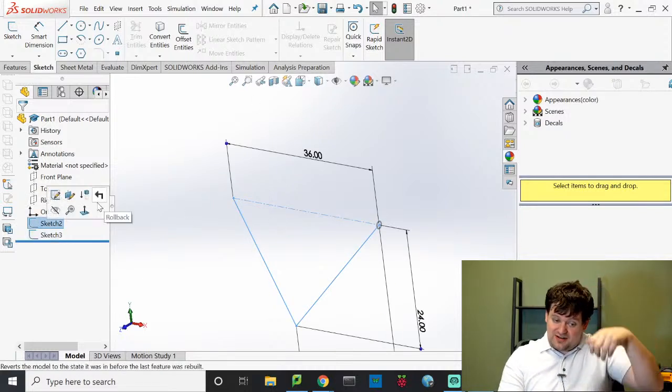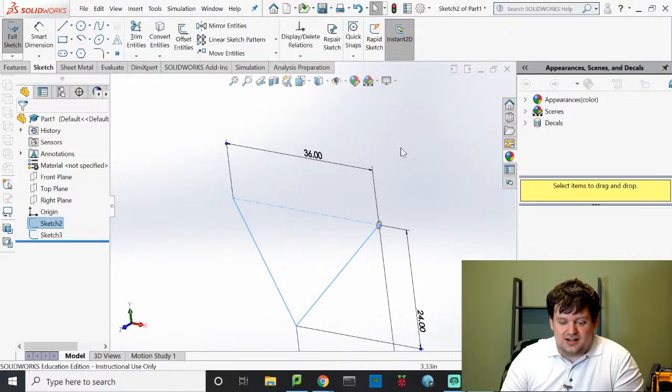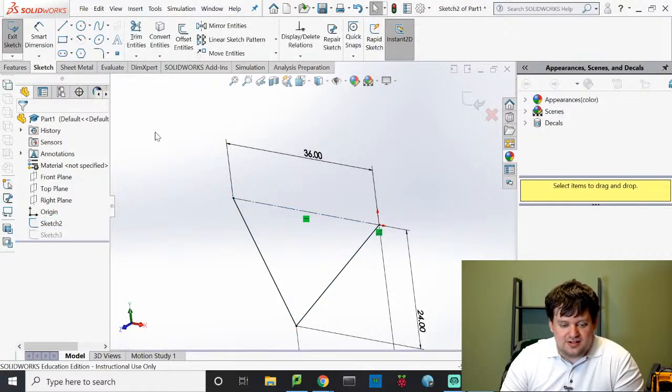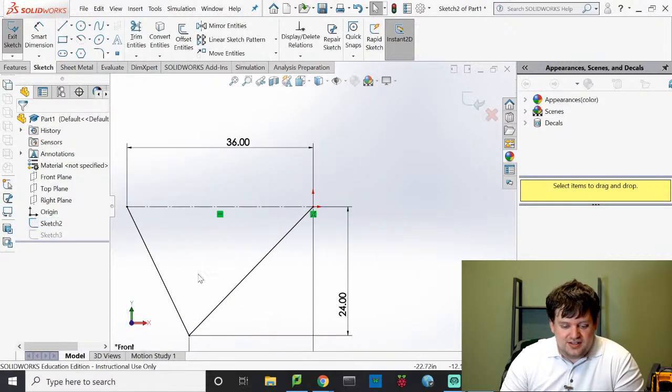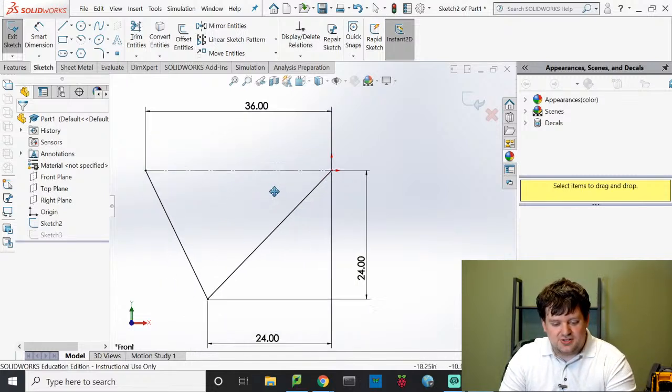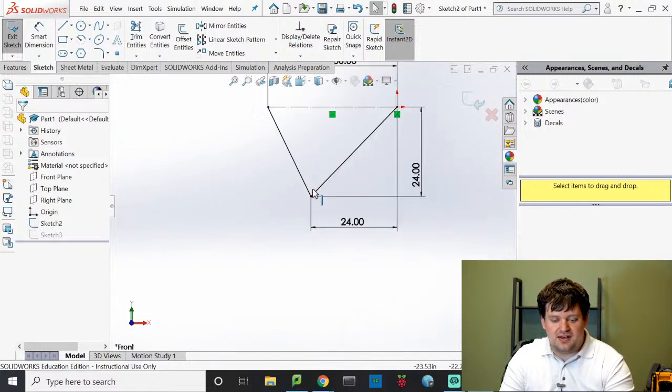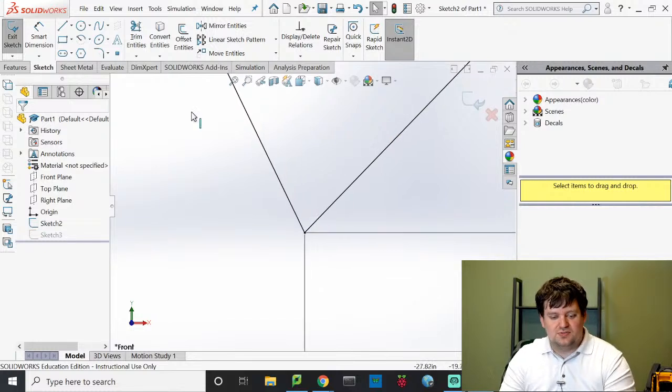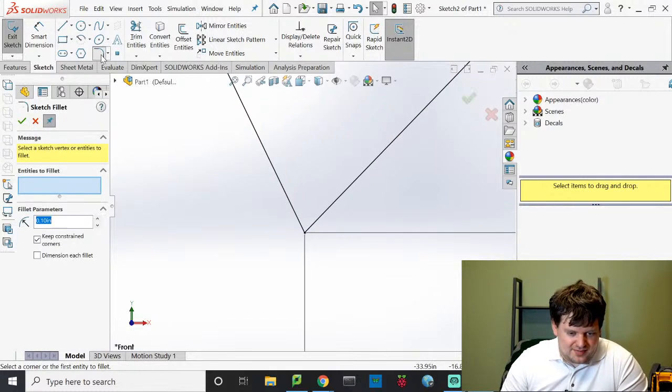I'm actually going to go back in. I forgot to put in an angle in here. I tried putting in a radius here earlier and forgot to finish that. So I'll zoom back in on this drawing, hit Control, drag my mouse wheel to pan, scroll my mouse wheel to zoom in here, and I'm just going to do a fillet.